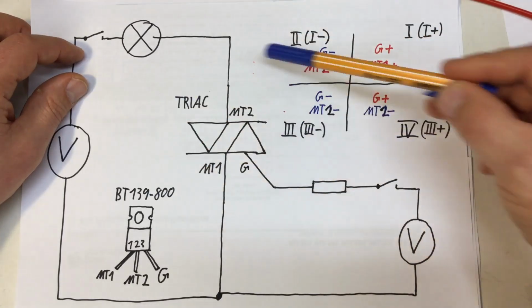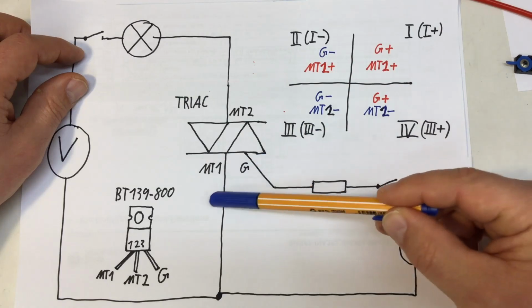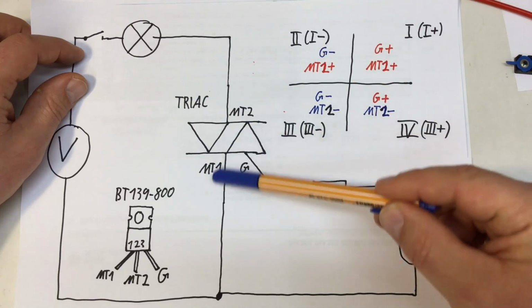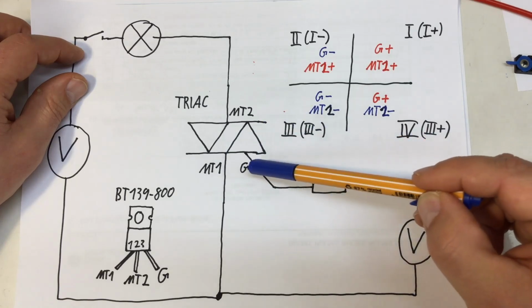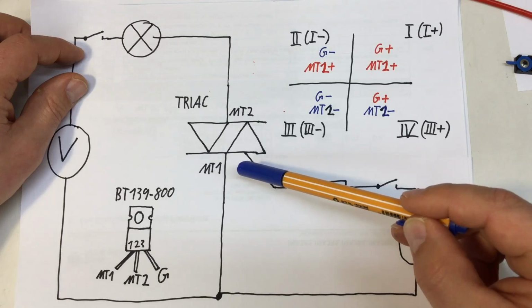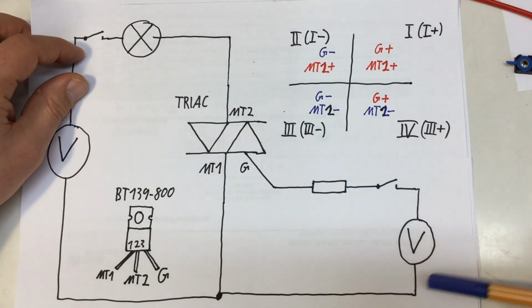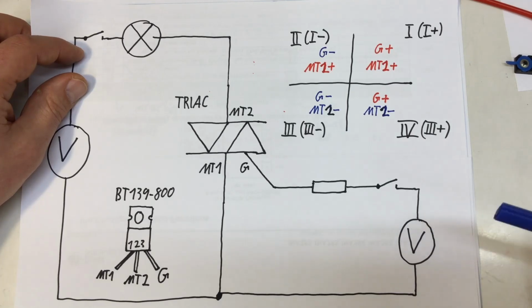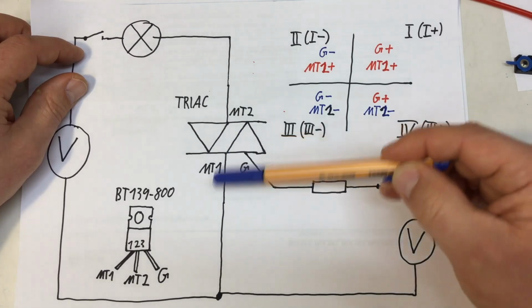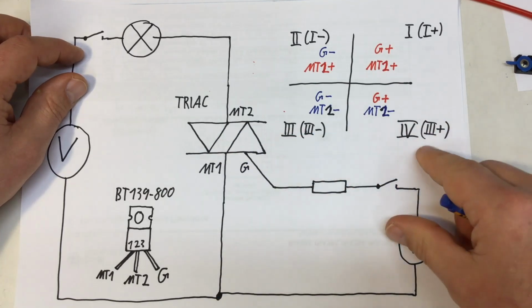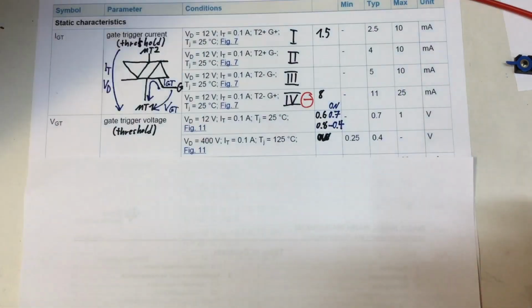If we are in quadrant 4, my voltage drop here in our example changed in the negative direction by minus 1.2 volts. That is, if I'm driving here with, let's say, the digital output of a 3.3 volt microcontroller, that's huge. Just something to keep in mind.